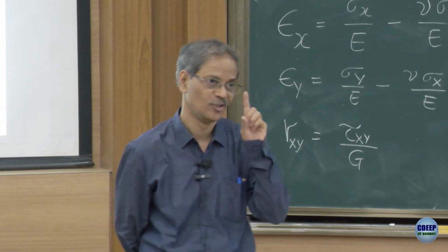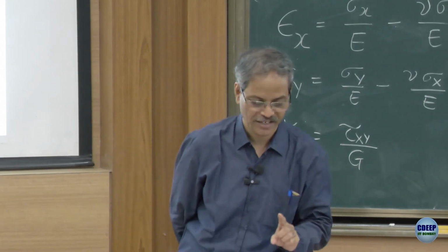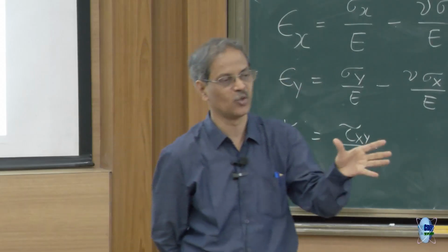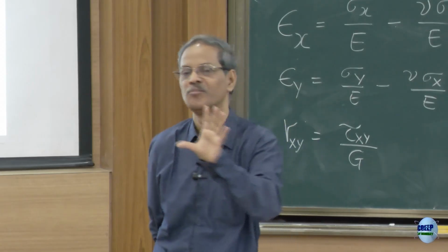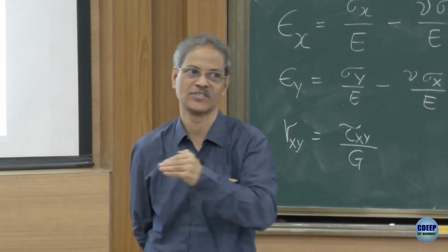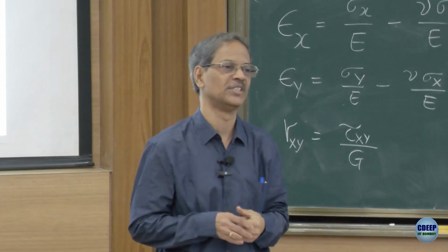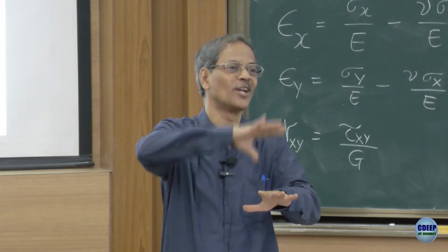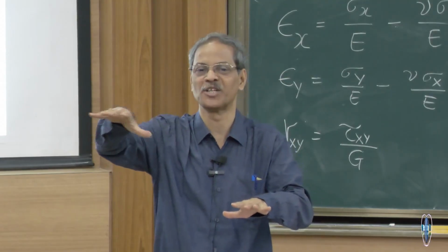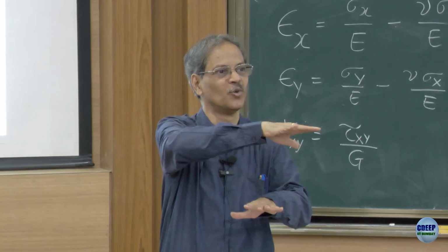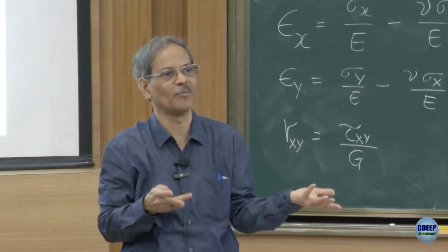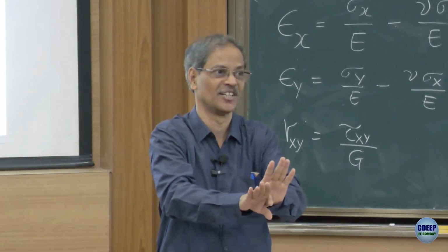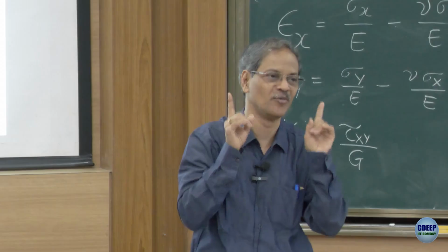So that's the first challenge we see, apart from, of course, dimensionality that I mentioned. Once you agree that it is a two-dimensional problem, this is the first major hurdle we are going to face. And a new error which we said is discretization error. I am not at all talking about the error in modeling the field variable variation, temperature, velocity, displacement. Both, I said, were there in the one-dimensional problem, and would be there in the two-dimensional problem also. In addition, you have brought in this new error. Keep that in mind when we are looking for an approximate solution.